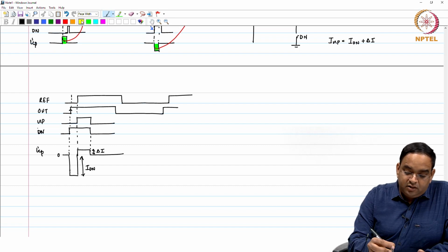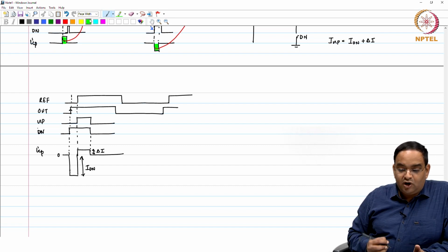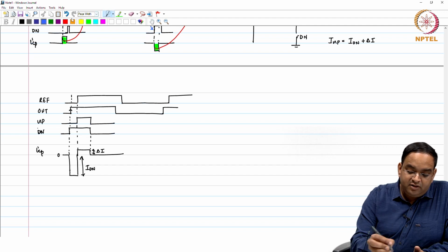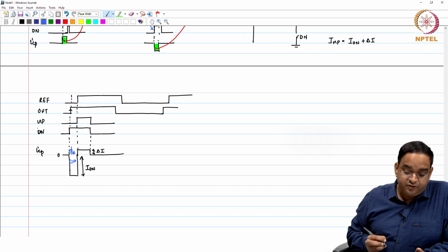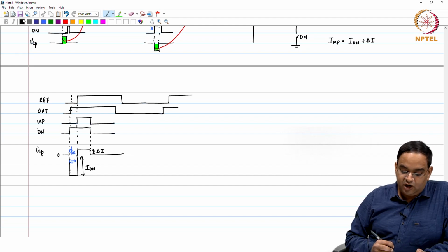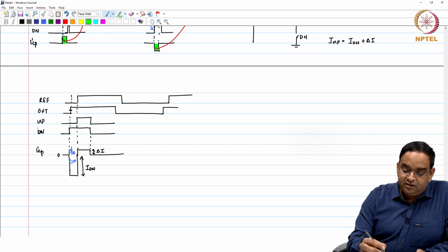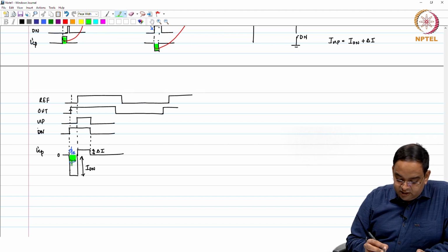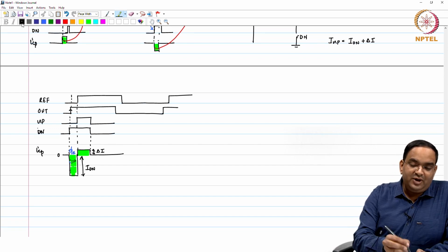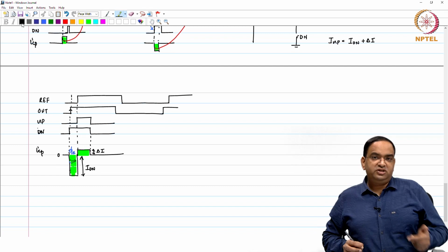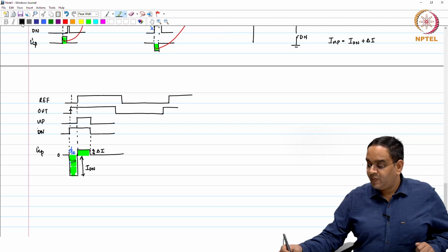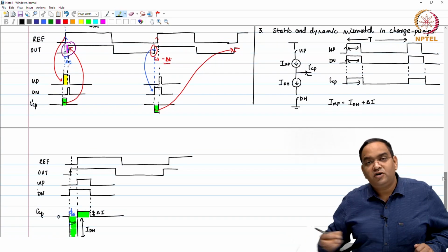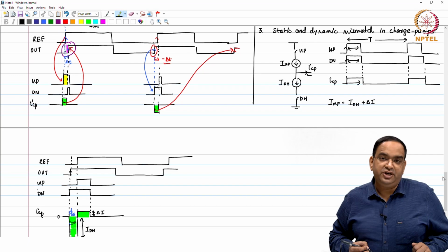So, the PLL is going to lock to a phase offset, and what is the phase offset, by the way? This is the phase offset, phi offset in the phase domain. So, it is going to lock to a phase offset in such a way that the total area under this curve is equal to 0. So, if you have any mismatch between the charge pump current sources, which is a source of nonlinearity in your PLL, you lock to a phase offset, not to 0 phase.